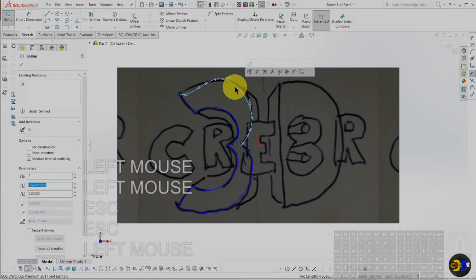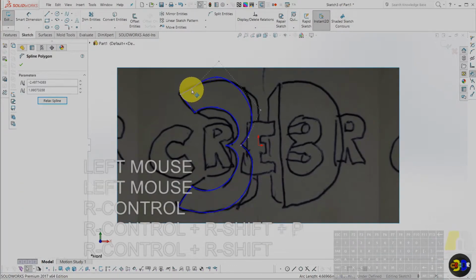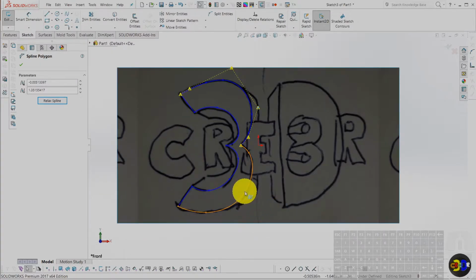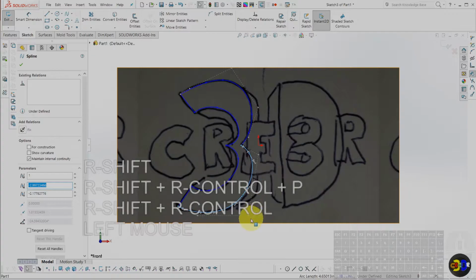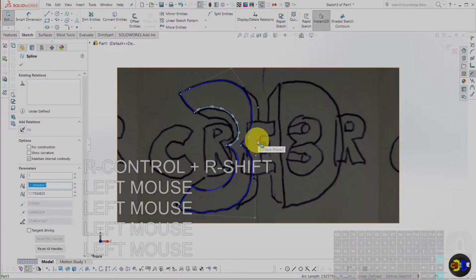And I'm going to go, I believe, Control Shift P for my control points. Yeah. Control Shift P shows me my control points for my spline, which allows me to adjust it. So I could do perfect arcs here and nice, perfect, clean offset, but I want it to be a little bit cartoony and not perfect like radii and things like that. I want splines that are not offset perfectly. It's a little more fun for my taste. That's a little too sharp.